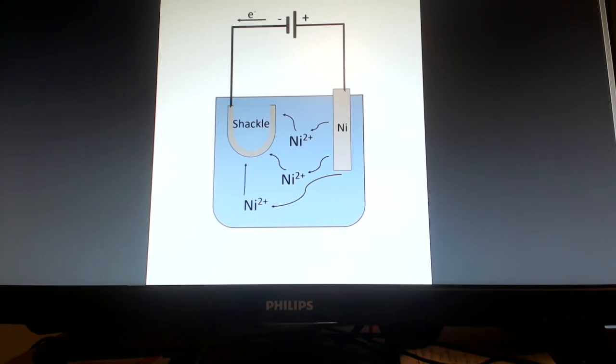This acts as a barrier coating for corrosion resistance, not as a sacrificial anode like zinc does in galvanization. So this just blocks the elements basically. This coating is more scratch and chip resistant than other coatings, such as zinc in the case of hot dip galvanization, as it's harder, and it's more scratch and chip resistant than painting and powder coating as well.